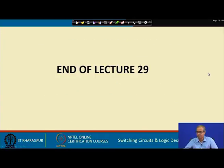With this we come to the end of this lecture. What we discussed in this lecture are, as I said, some unconventional ways in which you can represent some functions using AND and XOR gates. We saw how we can realize any arbitrary function using the Reed-Muller expression form, either in uncomplemented variables form or in the so-called fixed polarity form, where some variables are complemented and some variables are uncomplemented.